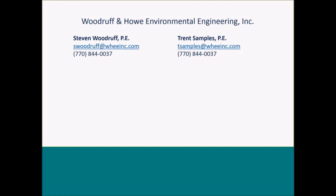So whether you're using sodium metabisulfite or the biological process itself is causing treatment of that, that's the assumption being made in the spreadsheet. Now, if you've got data indicating that there might be some PAA in the discharge, I think you probably need to take that into consideration. I do need to warn that some of those colorimetric testing kits for PAA are pretty unreliable and may not give you a good number.